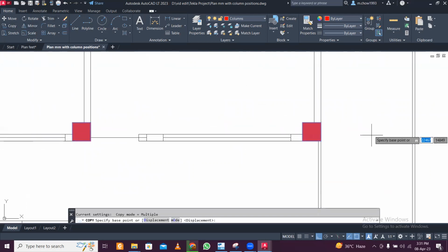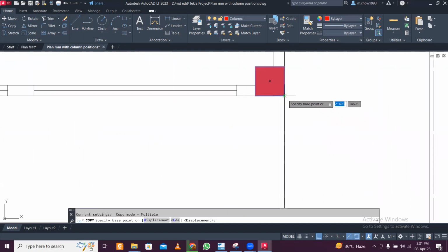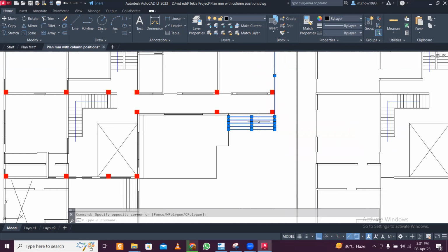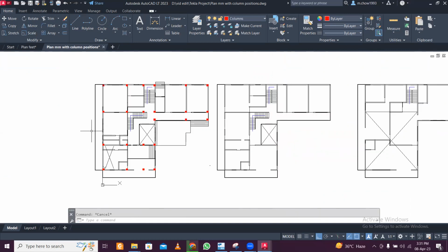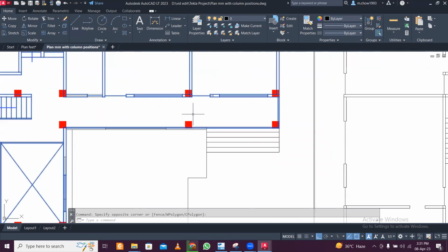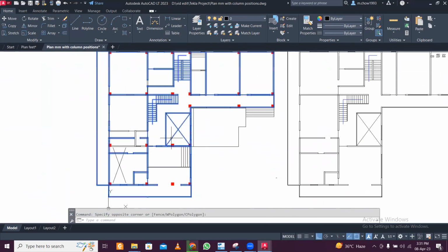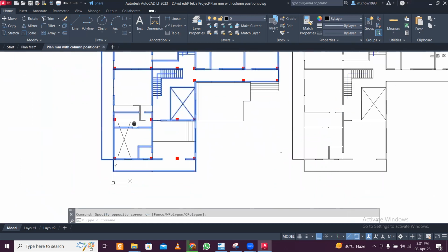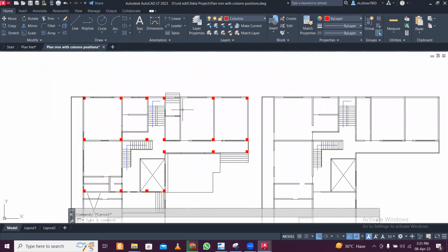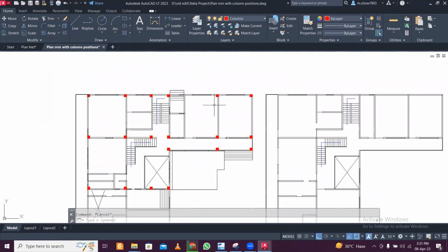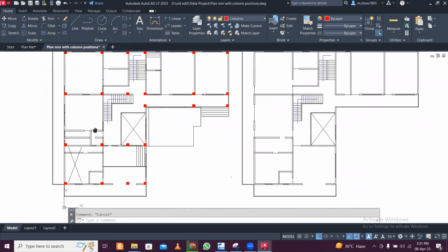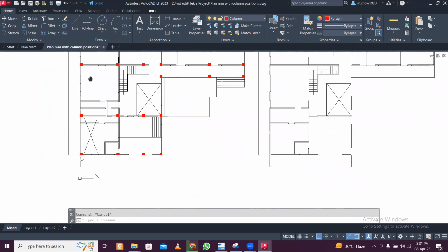But the reason I won't do that is I have to give columns here which are very close. This distance is around 5 feet apparently, but I have to give because the building ends here, right? This portion is the ground floor, and this portion, the first floor, you can see it ends here. So obviously, I need to give columns here. And regarding the depth of the beam, I think we could use more columns, but let's see. If that is too large, then we'll introduce a couple of columns here and a couple of columns here, and the structure will be reduced.